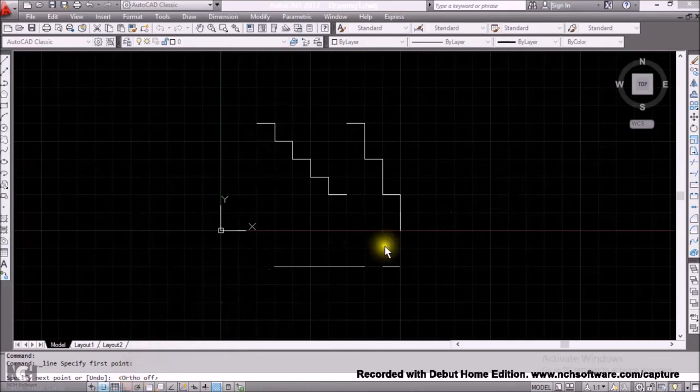If you deselect the ortho mode, you can place it anywhere, but if you click on the ortho mode, it constrains your cursor movement only to 2 directions, the X direction and the Y direction. Just two, no angular direction. So that is the work of the ortho mode, and you can perform this function using the F8 key on your computer keyboard.